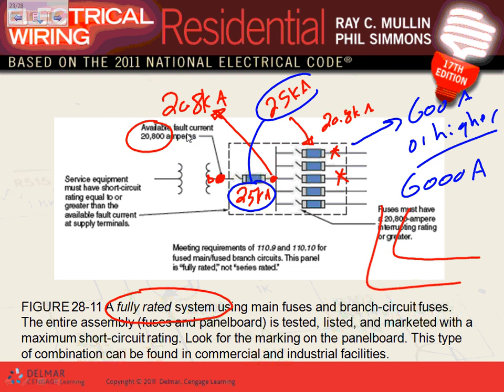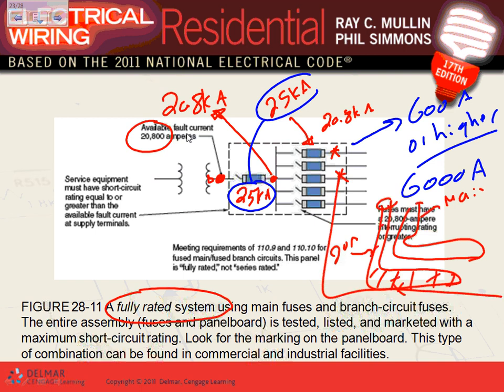So that will be one like this, that will be a circuit here and another circuit right here. If this is my main, and this is my, say, 20 amp right underneath it, and there's a short circuit, which one is going to see it? Right in here, the one underneath it.